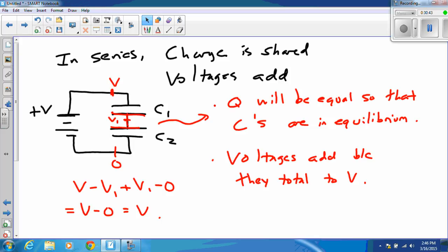Okay. So how do I know that these are the same? Because I look at the connections. If you take a look right here, all of the things in this row are connected to one another, and lo and behold, these two capacitors are in the same row. And nothing else is connected, which means these two are in series.